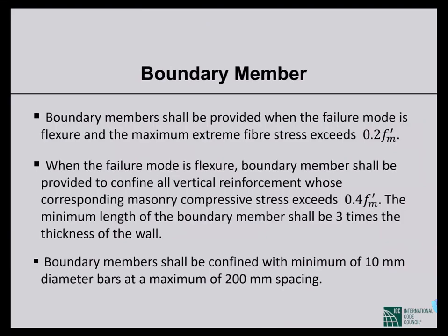In case of shear walls, we may have to use boundary members similar to reinforced concrete shear walls. In boundary members, we have to use ties with vertical reinforcement.